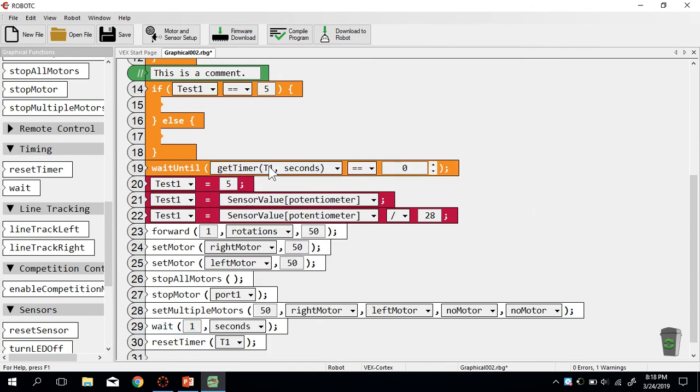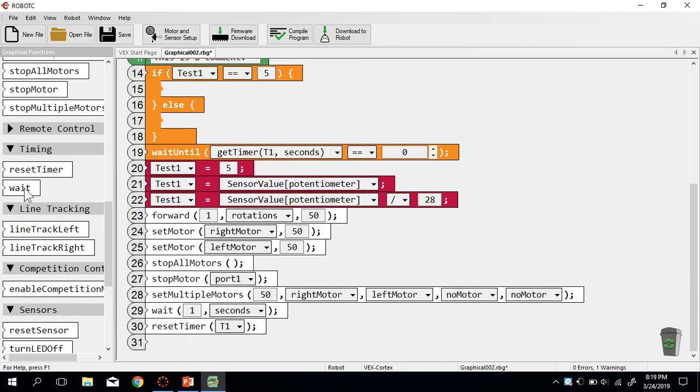After you use the timer, it's not going to automatically reset it. It's just going to keep running in the background. So you have to reset that timer if you want to reuse it. That's where you would reset it, and you select which of the timer variables. So if that's T1, you'd want to reset T1 before you use it, so it starts at 0. Or else all the timers essentially start when the program starts, and they just keep counting up indefinitely.